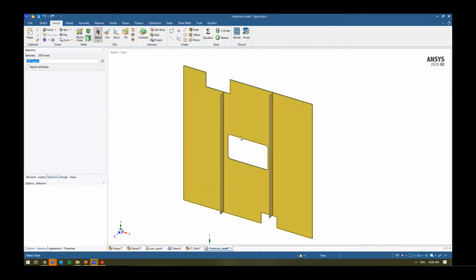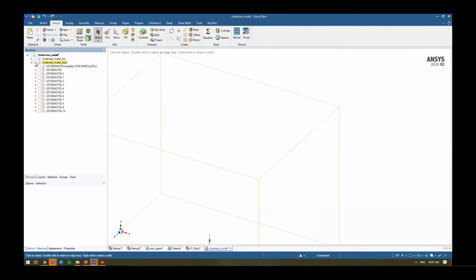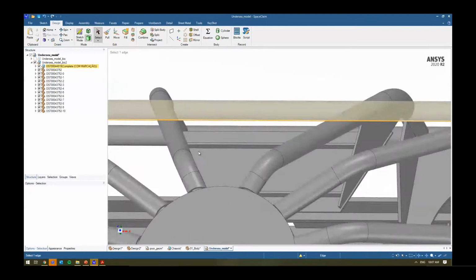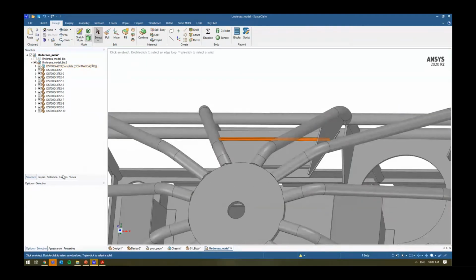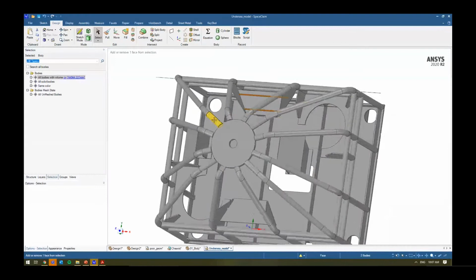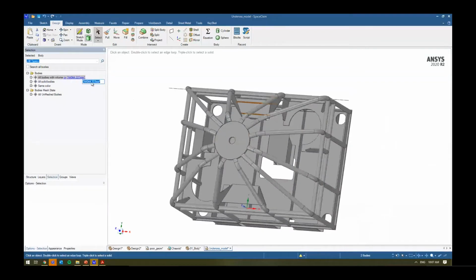So if you've got a lot of holes, or bolts, the easiest thing is you can select a face. Let's just say we go back and show everything. Let's just say we've got some small faces around here, right? We can select that, use my selection filter, and I want to select all volumes less than a specific number, and maybe I want to delete them because they might be all small bolt holes, right?